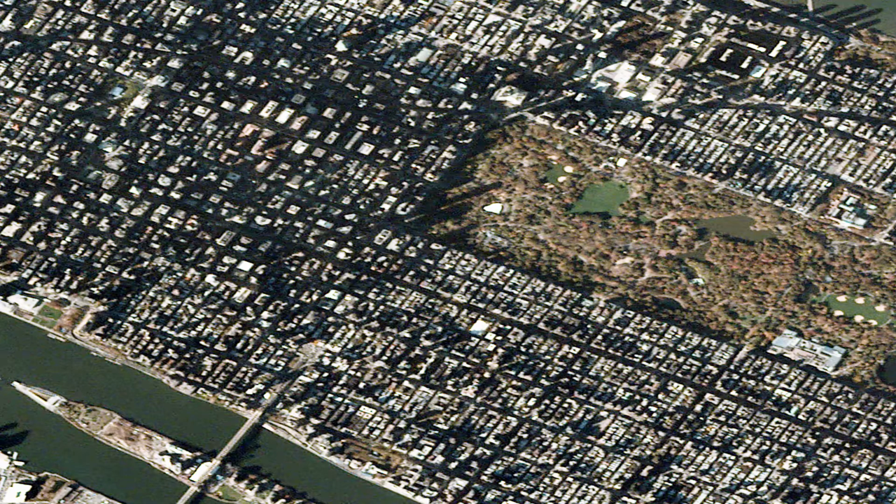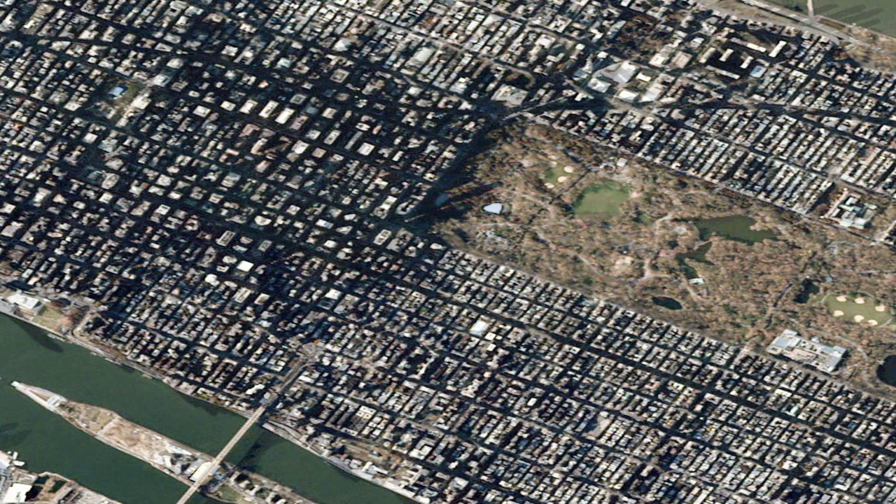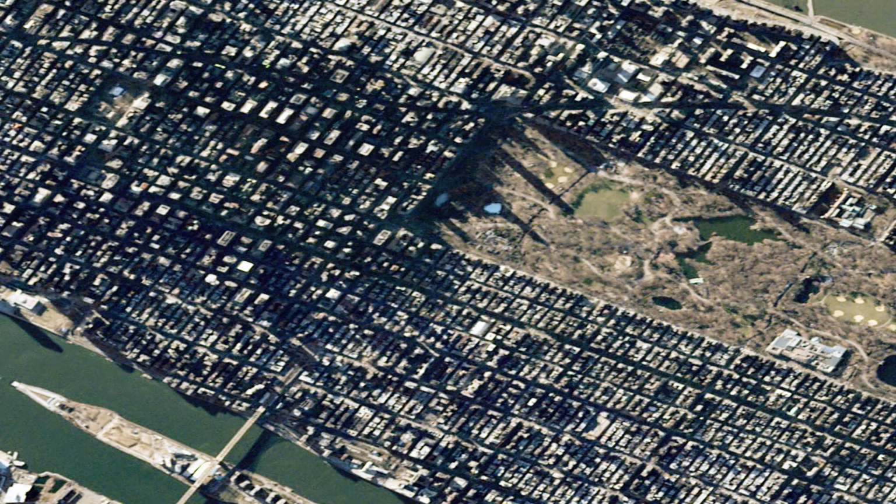In a given image, the brightness values for pixels of the same land cover type can vary substantially depending on whether they are situated in full sunlight, example south facing slopes in the northern hemisphere, or shadow. These effects are especially evident in areas of high relief. If such artifacts are not removed, they can significantly degrade results of multispectral classification.